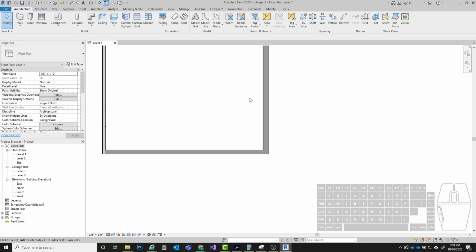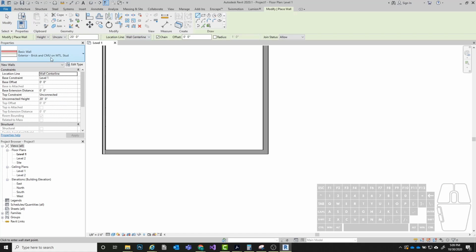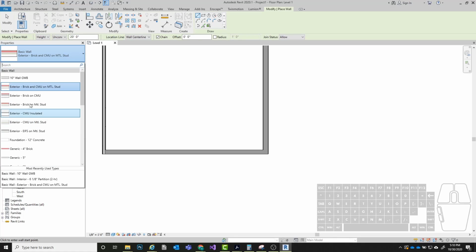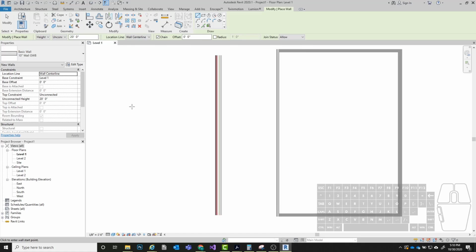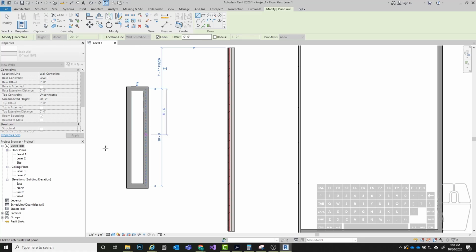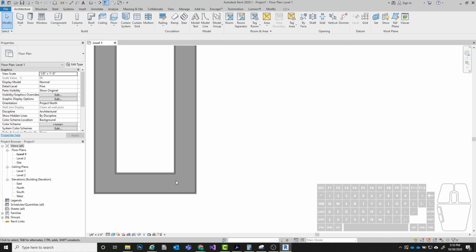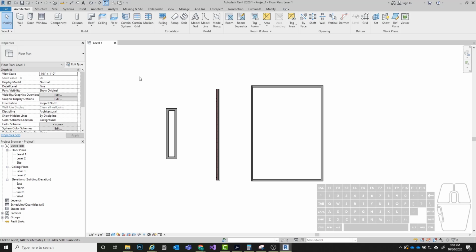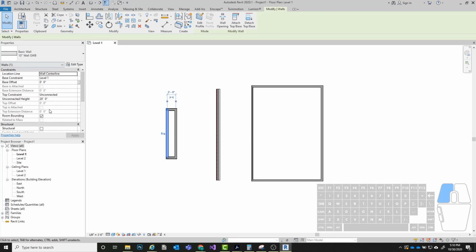And then if I were to go back to my wall section, so click on my wall tool, click on my drop down, you can see if I scroll down here, right here at the top, 10-inch wall gypsum wallboard is appearing inside of my menu, and I can click it and I can drag and I can draw as many of those as I want. All right, so that's how we go in and define custom wall types and understand sort of how this type selection menu works over here.